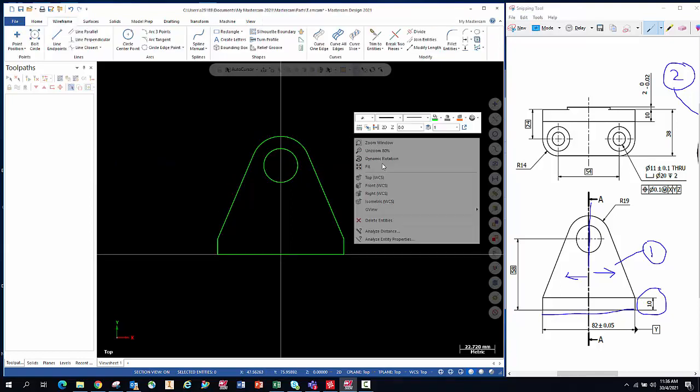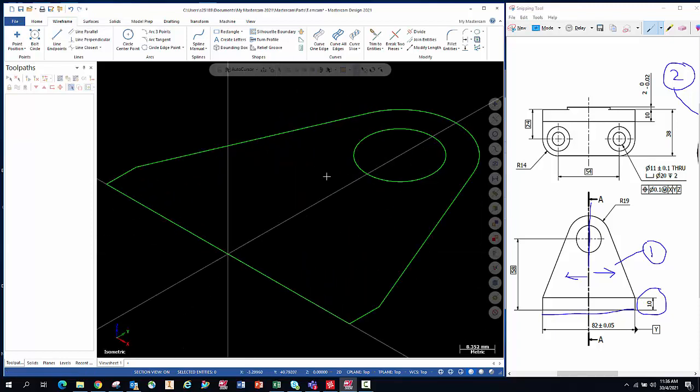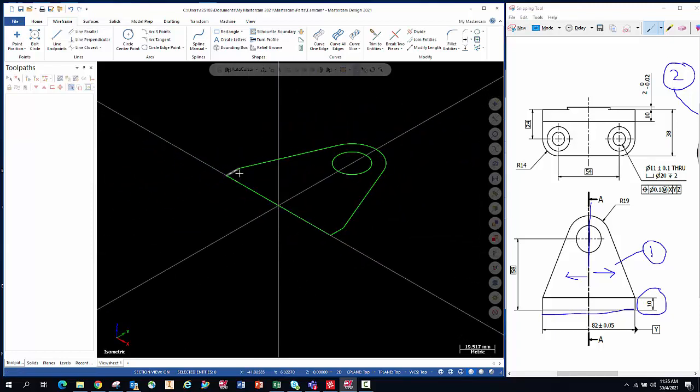Okay, so now if I go to isometric view, this is what I did. I did it on the Z0 plane over here. Now I will extrude this to become our first solid element. The thickness over here, you can see that this is having the value 10 mm. Okay, and come back here, I say levels. I like to put level 5, for example, which represents my solid.